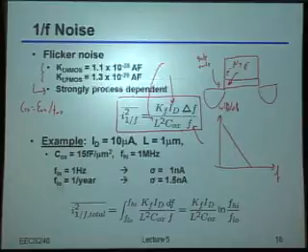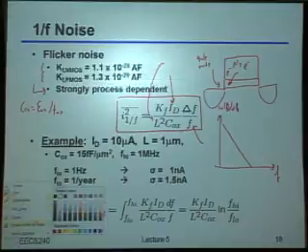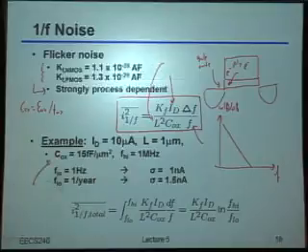Okay. So here I'm just giving you some example numbers for what that drain current density actually is. You can see that for something similar to our technology, where Cox is about 15 femtofarads per micron squared, then roughly speaking, if we look at the total integrated noise, you're going to get something on the order of a nanoamp to maybe 1.5 nanoamps.